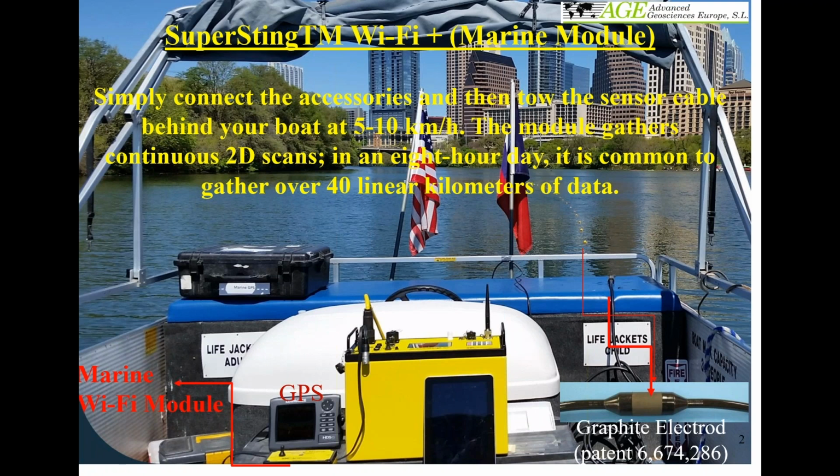However, if you have an older instrument, if you bought a SuperSting before 2014 and it doesn't have a Wi-Fi module, then if you want to do marine studies, like marine dynamic studies, you need to change the firmware of the instrument and put in the marine firmware.